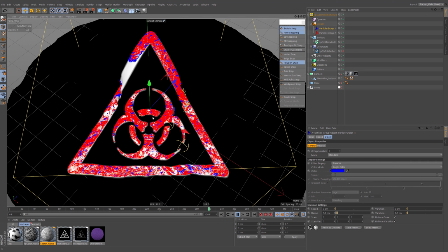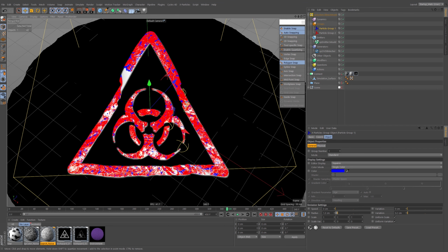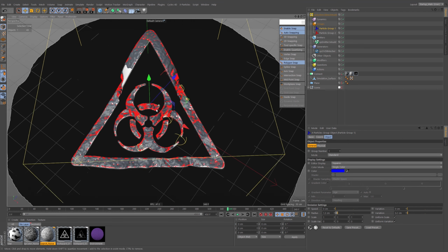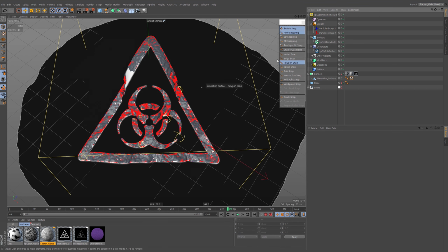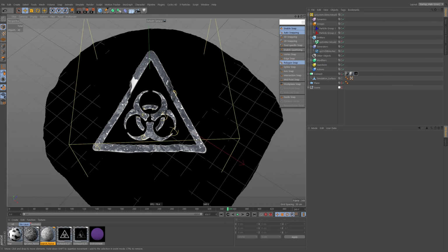Nature is beautiful. And so let's turn our OpenVDBMesher back on. You might have to nudge it a frame to get it to recalculate. There we go. All right, so that's looking quite interesting. Now, if I hide our emitter, that'll hide the particles, and I think that's looking pretty good.